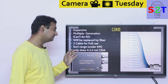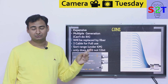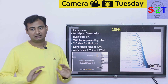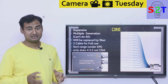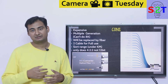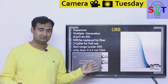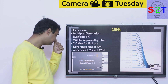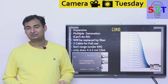So that created a problem that right now, as I talk to you, the common standard is 422, not 444, not 12-bit. You can't do 4444. Even though there are many cameras right now, including Blackmagic cameras, including Red Apex and Alexa Mini, that can do 4444, basically 12-bit recording, you can't transmit that using SDI. It's not built for that, because in the broadcasting industry there is no need for that.